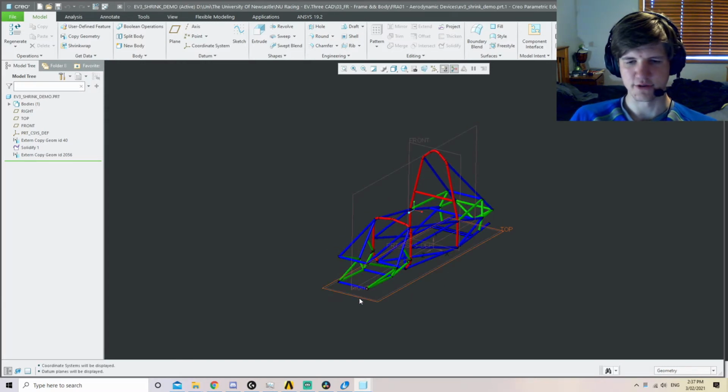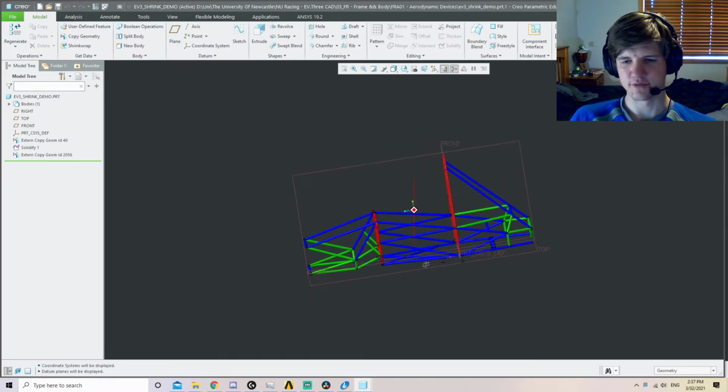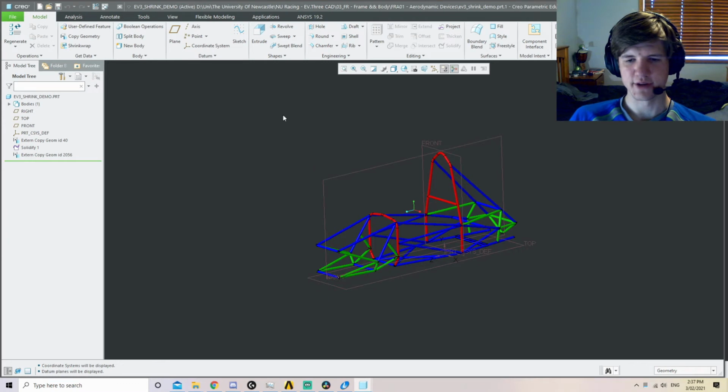Geometry is created as normal for Creo, and additional planes can be added to start geometry creation from where desired. The goal here is to make this chassis into a rough solid replica of the car to put into ANSYS in a single part. This can be done over the top of the chassis or in a separate file using the analysis tool to determine distances between locations.